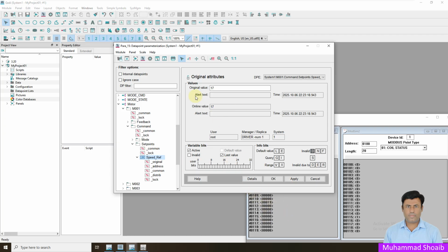Because if you have the SCADA system also and a local HMI also, if somebody changes some value in the local HMI and you want to update that same value in the SCADA, you must configure read write at the data point. So right now somebody from the field changed the value through the HMI to a 19 set point, but here it's not updating. So what common mistake are people usually making?